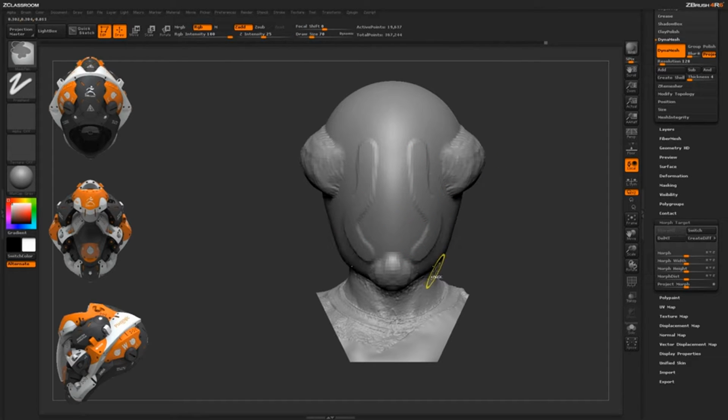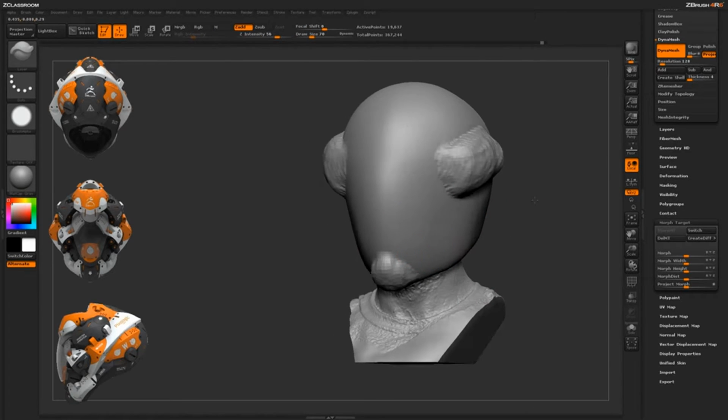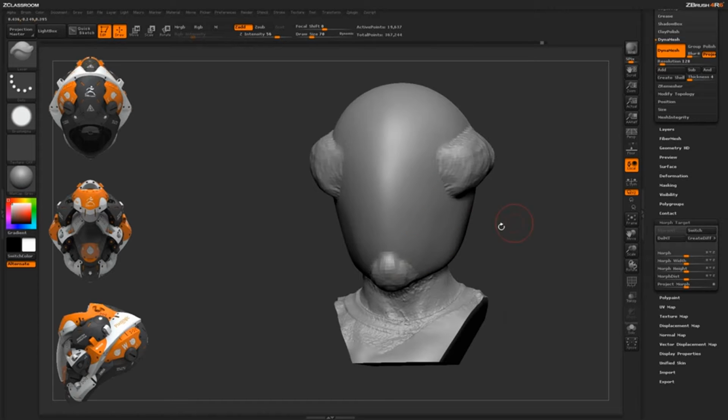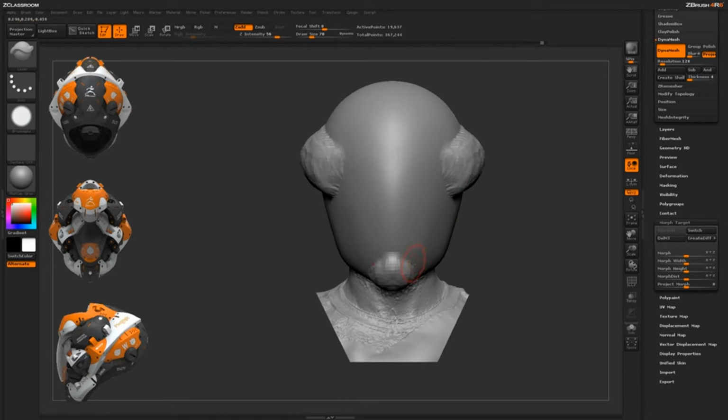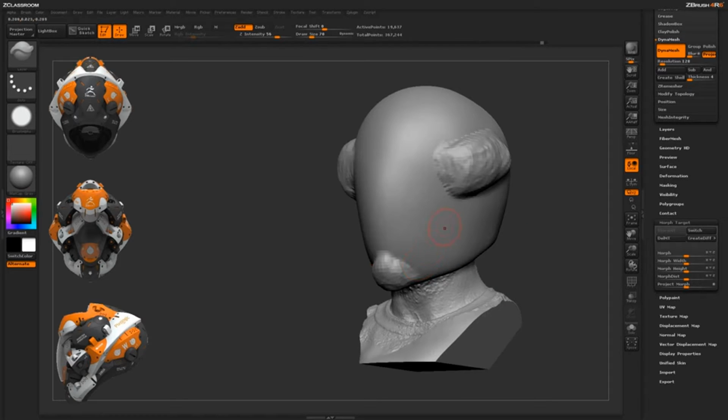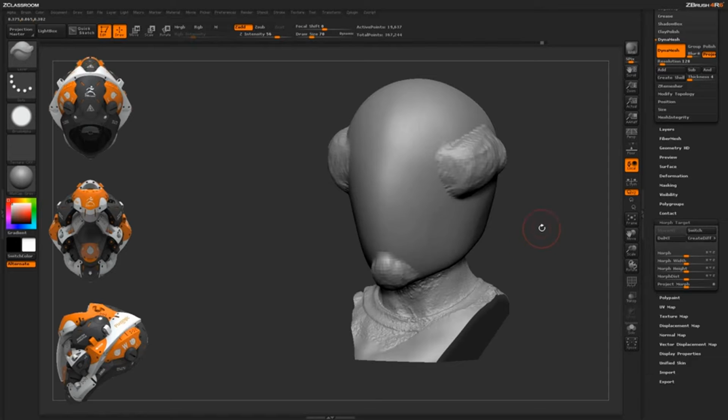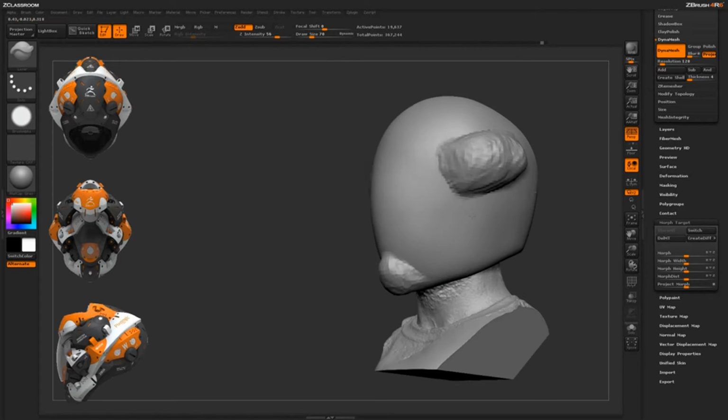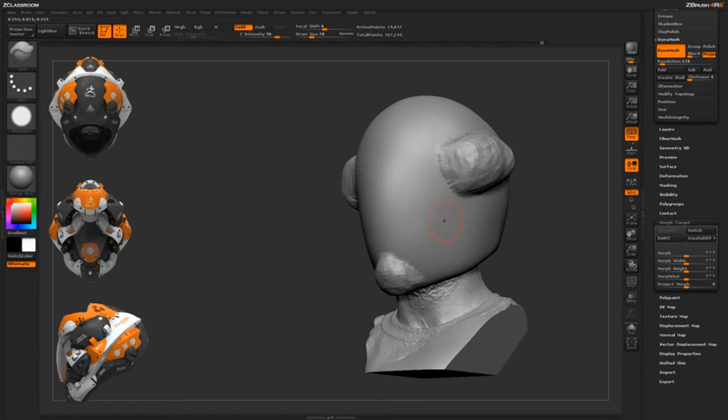One thing to look out for when you're using this is to make sure you're giving enough thickness with your intensity, because we're going to turn it into a mesh, and if you have really thin areas of geometry on your newly generated mesh from that create difference brush, you could end up with some issues when you're trying to sculpt on that piece later.